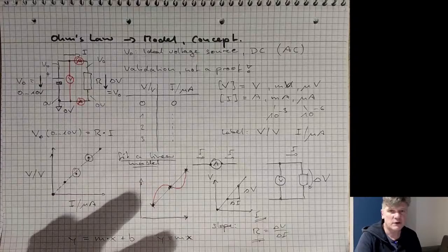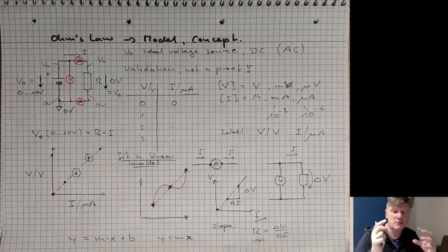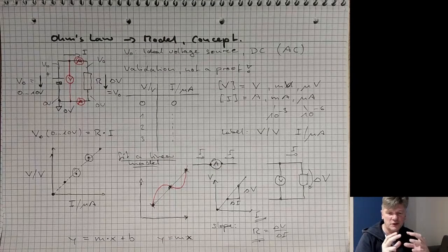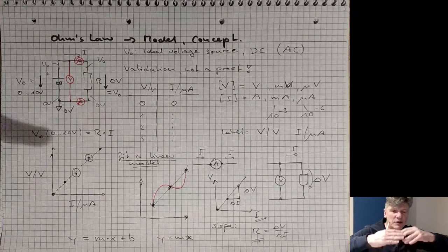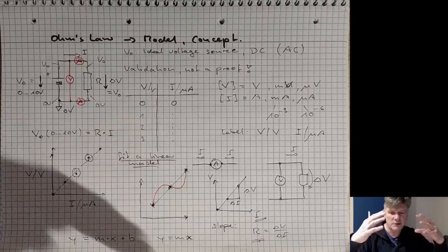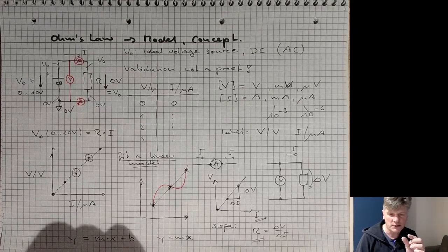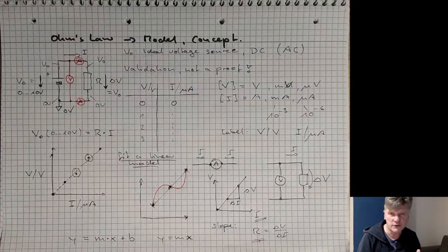If you have a large resistor, you can imagine this is more rugged, you have a large surface. I'm not talking about the value of the resistor, I'm talking about the physical properties of the resistor. Is it a tiny one or is it a big one? When you have a big one, then the thermal load is basically distributed over a larger surface, a larger volume, and the system is more relaxed. If you have a small resistor with the same resistor value, right, you can technically solve this, then that gets really stressed.